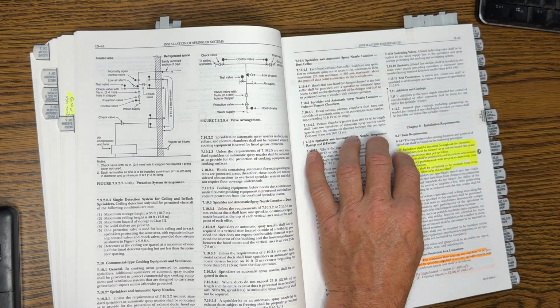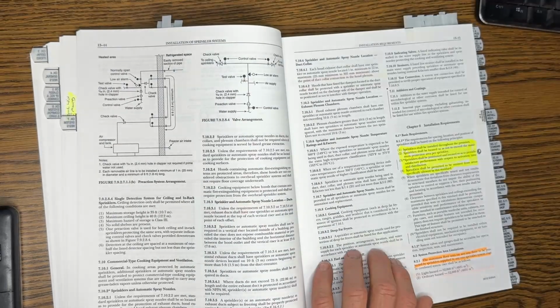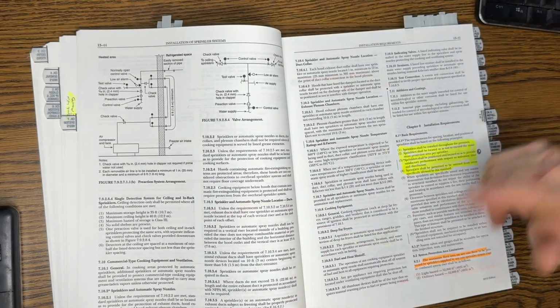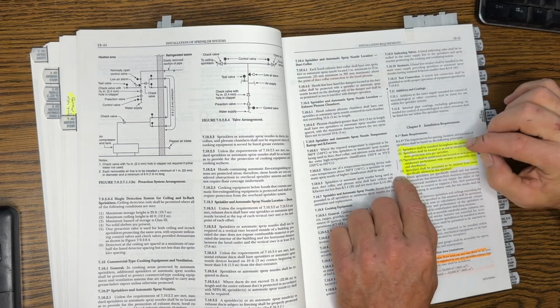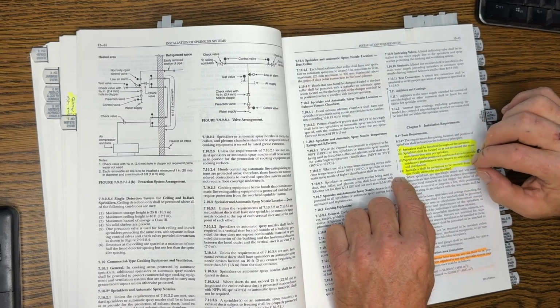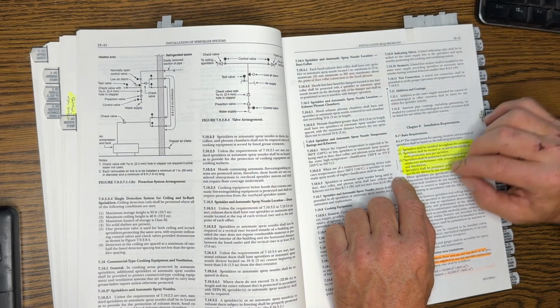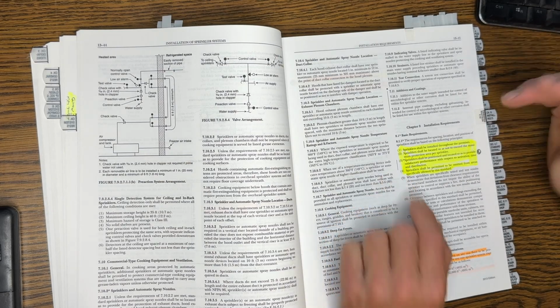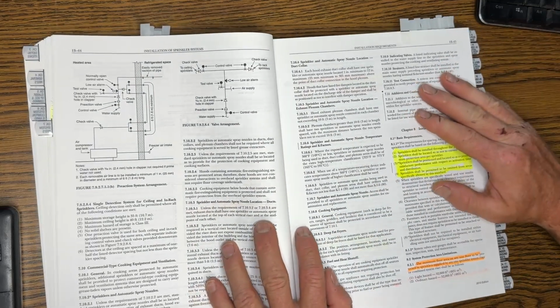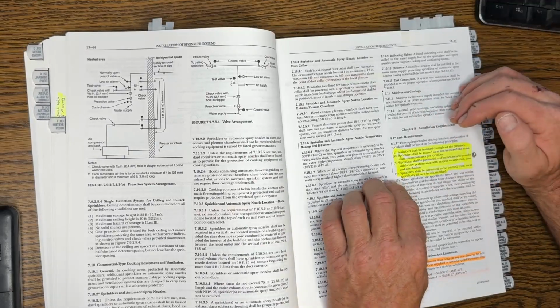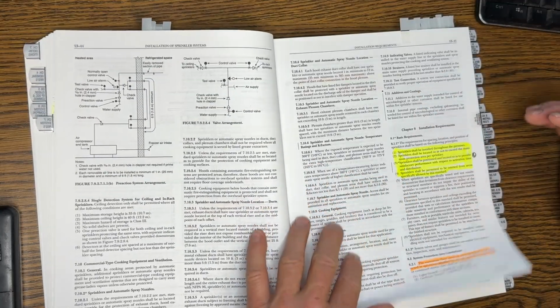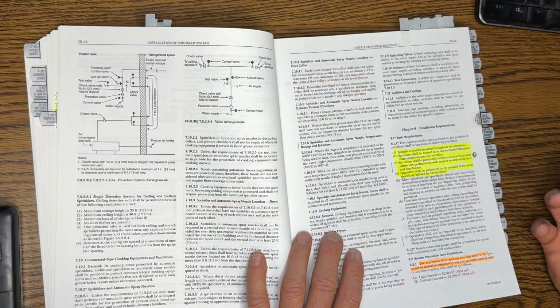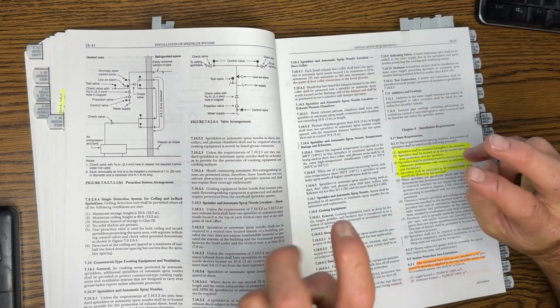because if you go back to that section I showed you in the IFC and you specifically look at the commentary, I'm not going to take the time to look it up. They're very strict, saying you can't just willy-nilly omit stuff from what defines undesirable. So it becomes very murky in terms of how to interpret this. So just keep in mind, you can get rid of sprinklers from undesirable locations.